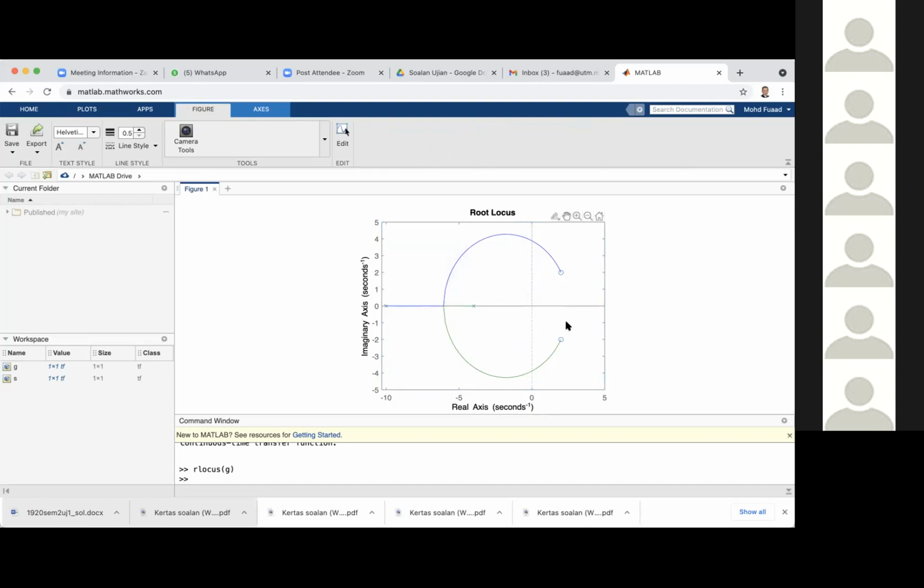The root locus crosses the imaginary axis over here, at 3.84. Our answer is 3.84, and the poles are at plus or minus j3.84. The problem with this online version is you cannot scan. I tried to drag the point, it didn't work.